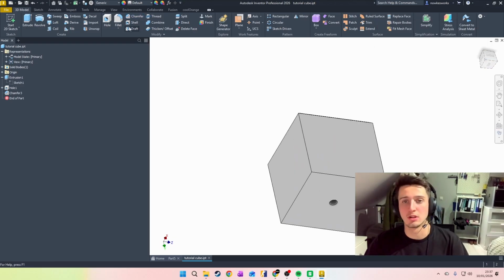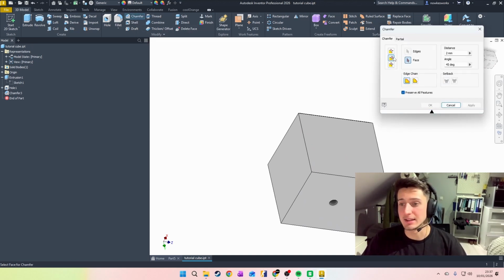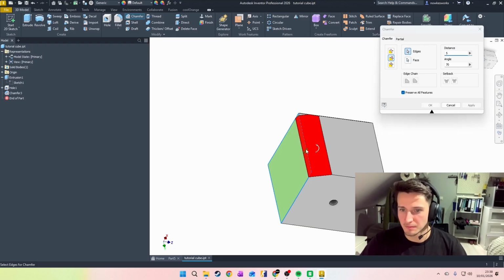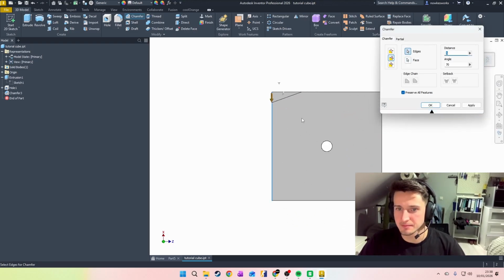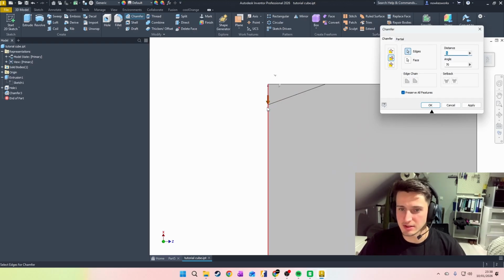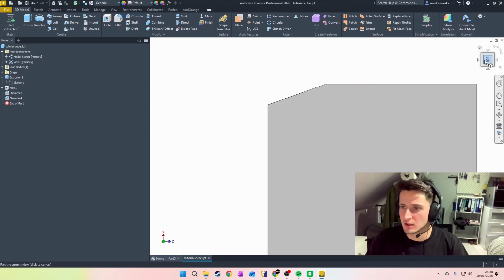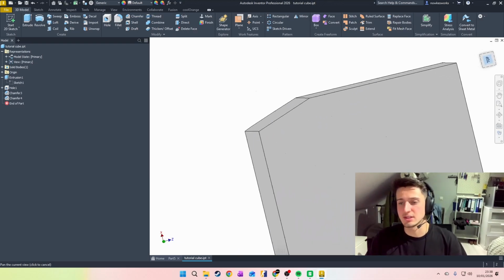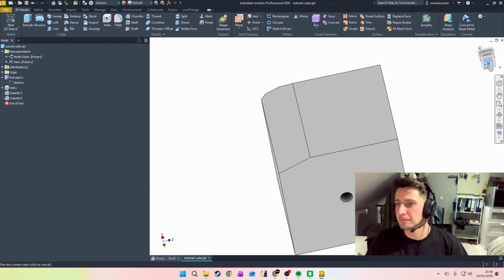But then we can also make different types of chamfers. Let's say the distance and an angle. So we want this face to this face. We want let's say 70-degree angle with a distance of 5 millimeter. And then you see it's 5 millimeters this side, and then this corner of 70 degrees. Apply. So in some cases this might be useful, but I don't use it that often.